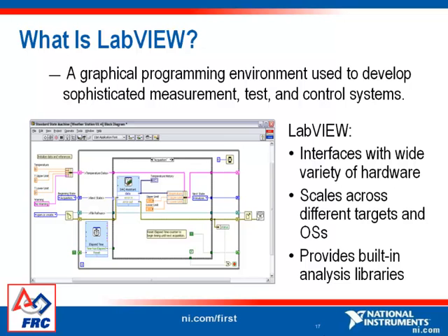You're going to have functions, which are blocks of code that are pictures that look like what they're supposed to do. They give out data onto wires. The data travels along the wires between the functions, and sometimes the wires go to where the user can see them so that you can see the data that's on the wires. This maps onto robotics problems very well because signals come into the robot controller through these functions and pass around on the wires just like they pass around in the electrical wires to get into the controller. Then they pass out to go to things like the motors and the other sensors.